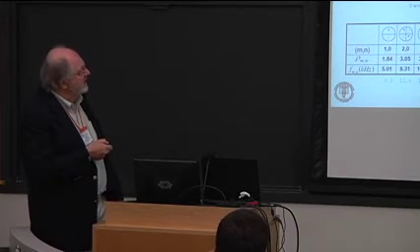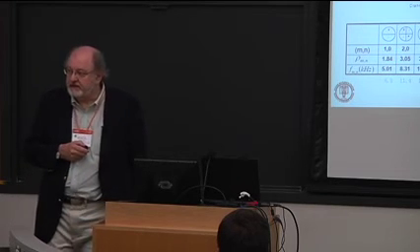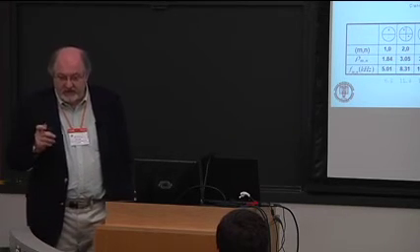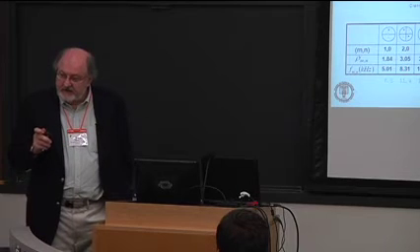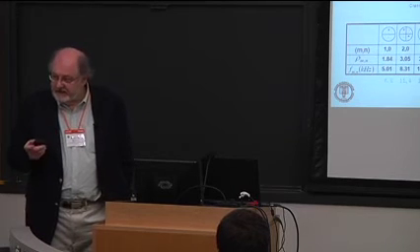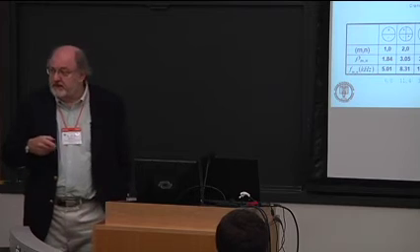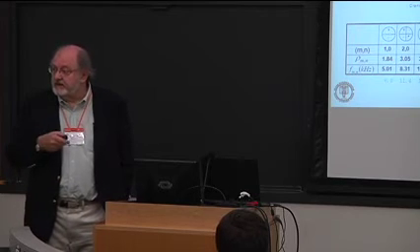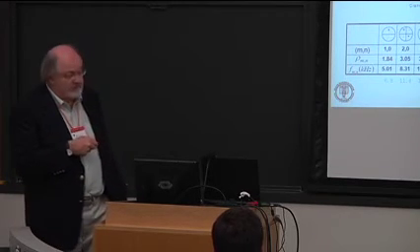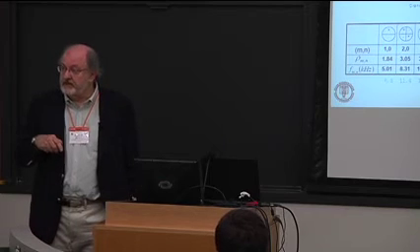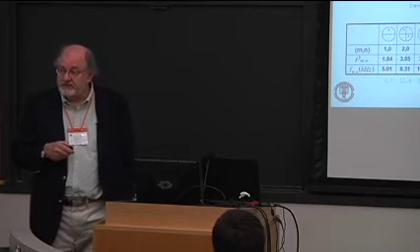So here we're changing the time step from 10 microseconds to 0.1 microsecond. First thing is that if you look at the number of crank angles that are represented by, say, 10 microseconds, it tells you what frequency you could expect to see in these pictures. So you need to have a small time step in order to get those high frequency components.